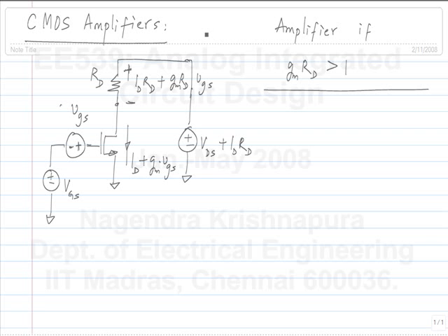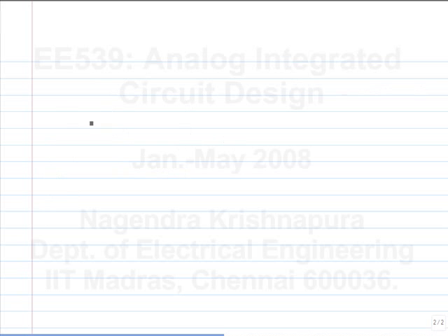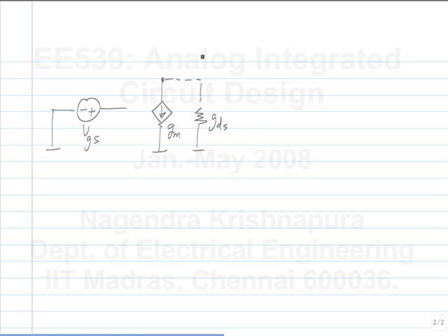Go on increasing the input increment, the size of the input increment VGS. What happens? Will the output increment go on increasing? We go out of saturation region. So far, we have assumed that the small signal picture or the incremental picture is this, right? In the incremental picture, the bias source VGS is grounded. We have this one and GM, and normally there would be GDS also, which we have ignored, RD, and the top of RD also goes to ground through the voltage source in the incremental picture.